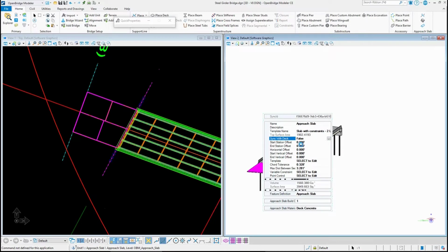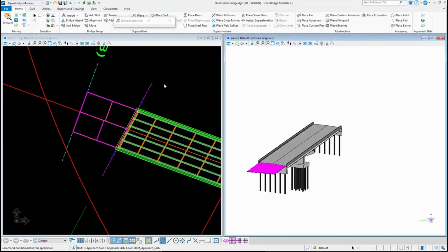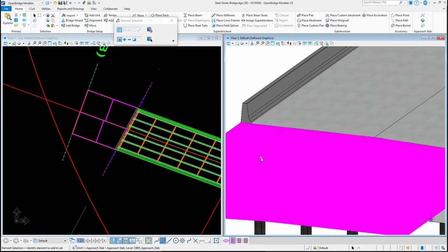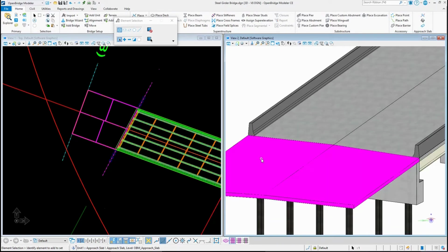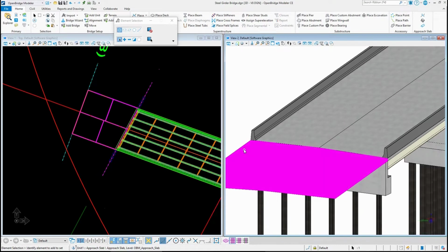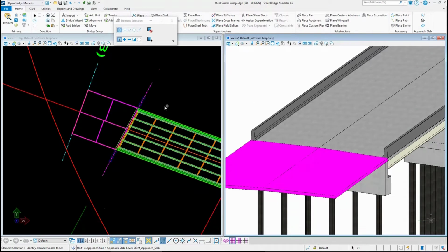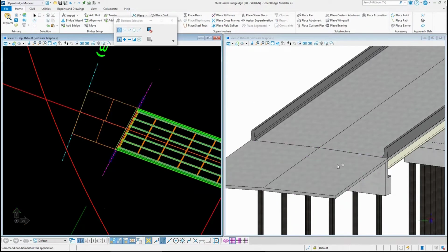And then it's just going to take the deck, the template, and put it at the proper skew angle and everything else. So it is completely synchronized with the width of the deck and everything else. So I don't need to worry too much about it. So that is the option of synchronize with the deck. Now the other options, horizontal offset, the stage of offset, not something that we use typically, but synchronize with the deck is the option I want to show.